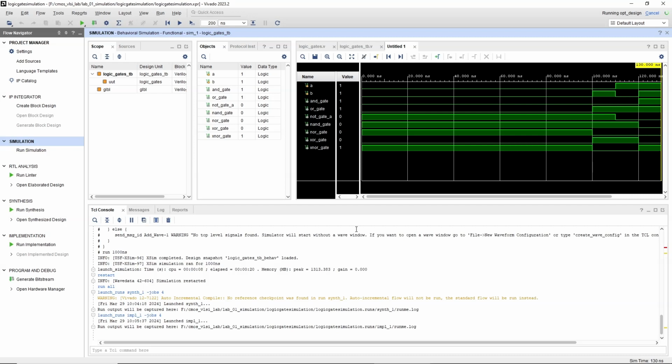Design rule checks, DRC, are performed to verify that the FPGA design meets all specified requirements and industry standards. The outcome of the implementation phase is a fully mapped design, ready to be loaded onto the FPGA for testing and deployment. This step is pivotal, as it transitions your project from a theoretical design to a tangible, operational FPGA configuration.